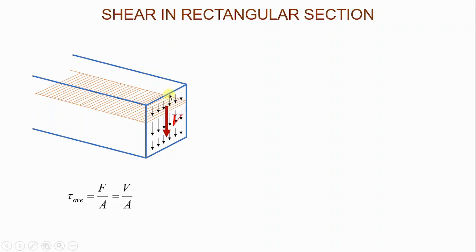So if you go 200 millimeters from the top going down and you draw a horizontal line, then that plane that you get there, the magnitude of the shear stress anywhere on that plane, that is what we are looking for. As you can see, it was drawn like that. You just had the line here and they ask you what is the magnitude of the shear stress on this line, but what is really meant by that is the magnitude of the shear stress on the horizontal plane here. Very important to understand that.